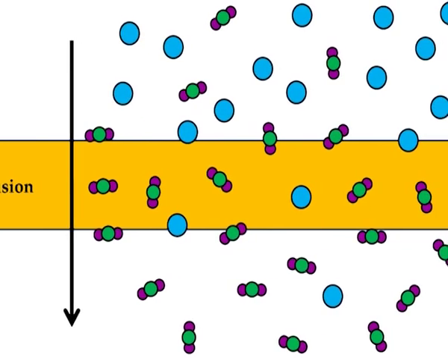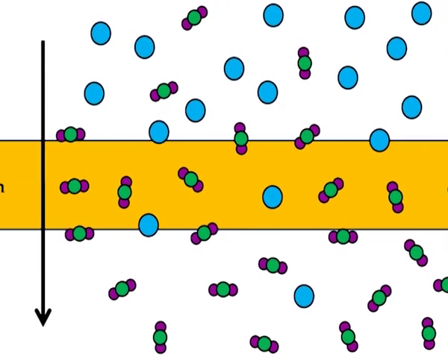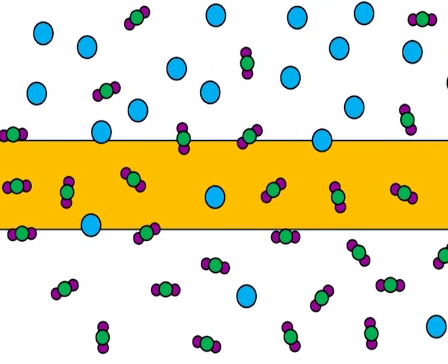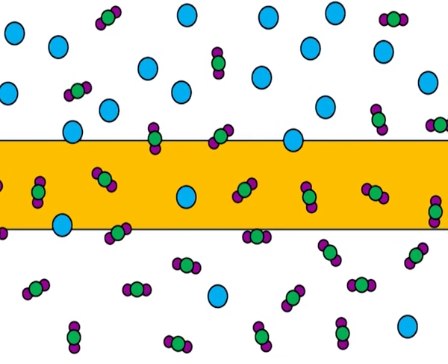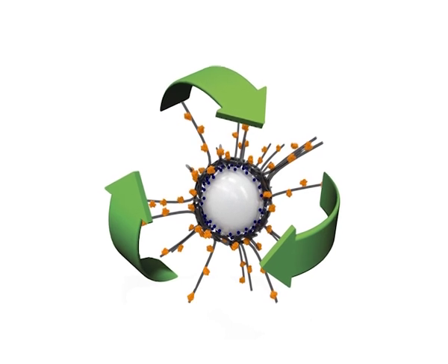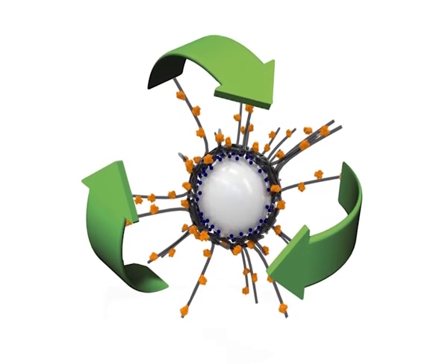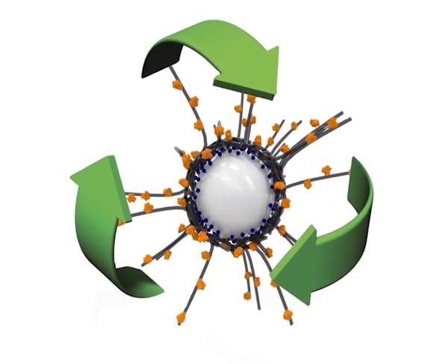Therefore, porous supports are generally preferred because the high surface area allows for a higher enzyme loading and the immobilized enzyme receives greater protection from the environment. Porous supports should have a controlled pore distribution in order to optimize capacity and flow properties. In spite of the many advantages of inorganic carriers, for example, high stability against physical, chemical and microbial degradation, most of the industrial applications are performed with organic matrices.